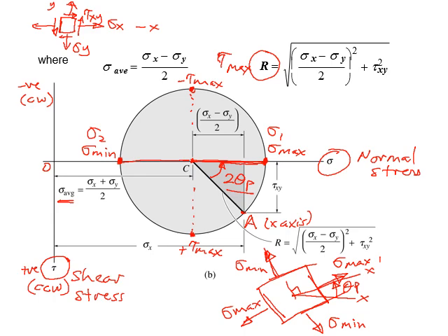Okay, so that is how useful this Mohr circle is, to help us visualize what happens to the stress element and where we can easily find the maximum and minimum stresses acting, right? And you won't make a mistake. So we have sigma max and sigma min. And the other thing you can notice is, at the point where we have sigma max and sigma min, it is on the axis of normal stress.